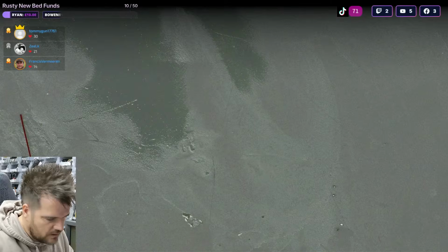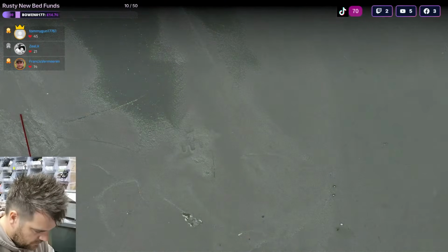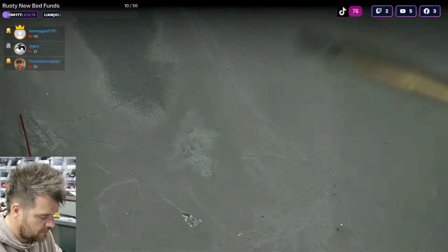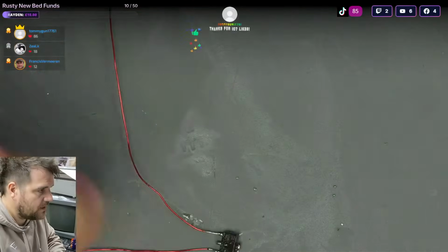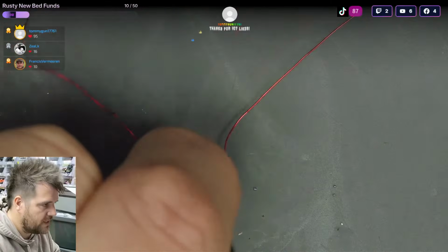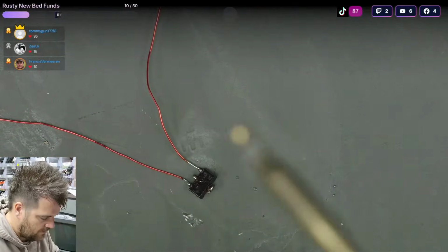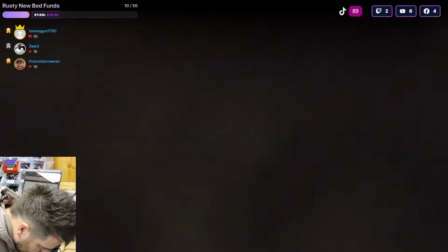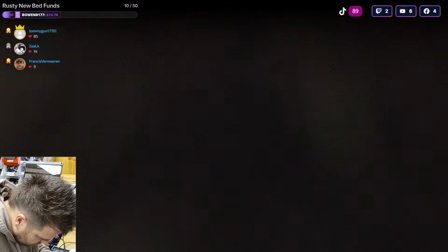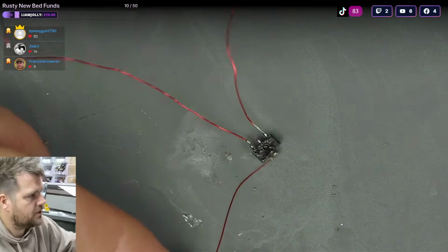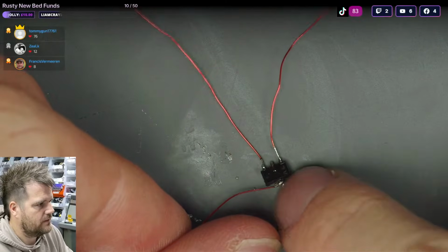Right, so hopefully we have got to do this quite a few times. I was going to say, hopefully we haven't got to do this amount of work on every component, but looks like all the transistors are like this. But the benefit here is I'm going to have these wires pre-stripped, pre-tinned and saved in between testing, so all I'll have to do is tack the 3 wires on, and I'll leave them attached to the tester as well, so it won't be anywhere near as long as this then. We'll just have to tack 3 solder pads on each one. And the middle pin is attached to the tab at the back as well, so that is effectively the same as that middle pin.